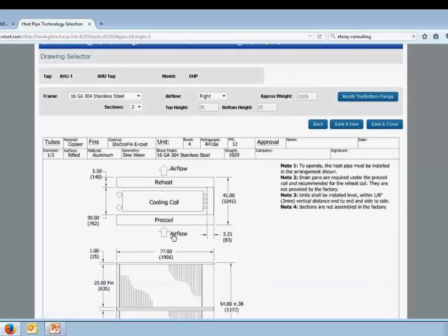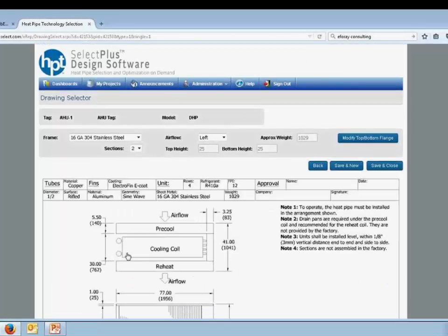So if you're standing here with the air hitting you in the back of the head, just our hand, what we use as handing, for this it would be a left-hand chill water coil, but in our case we do our piping around the U-bend side of your cooling coil. So for us this would be a right-hand coil or right-hand U-frame. So it's generally the opposite of what your handing is on your cooling coil. So something to keep in mind, if this was a left airflow for us, this would be a right-hand cooling coil for yourself. Again, in the design process, it's really not that important because the performance or price or anything doesn't change. It's just important to look at when you are about to order.